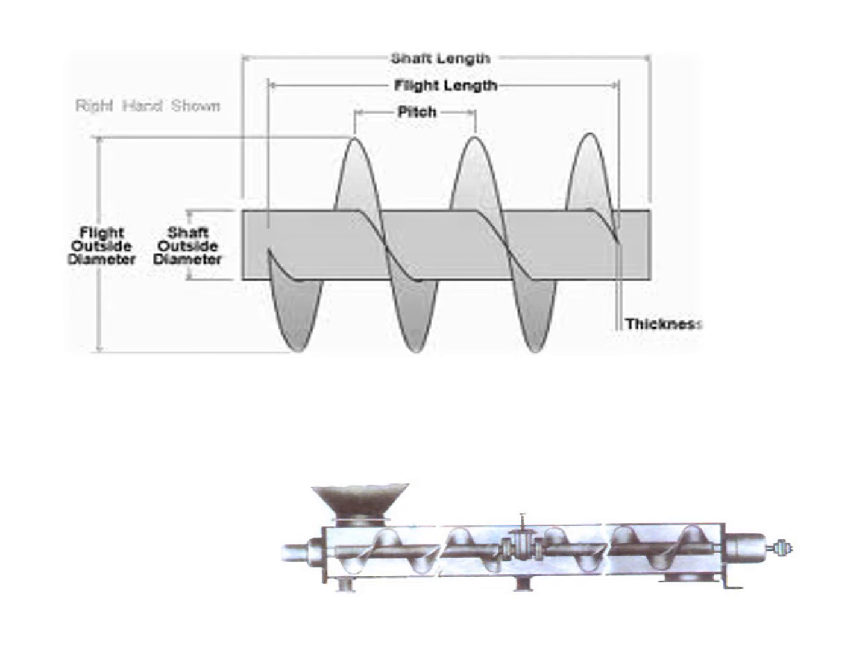The capacity of a screw conveyor is influenced by the screw diameter, inclination of the screw blade, speed of the blade, shaft diameter, and cross section of loading. The theoretical capacity is more than the actual capacity because of screw housing clearance and the loading factor.